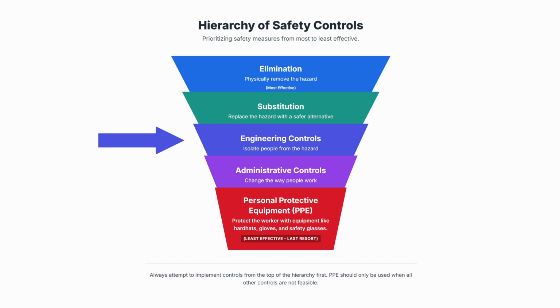Step 4. Develop mitigation strategies. There are several mitigation options that can be used to reduce occurrence and/or severity of a risk. Engineering controls, like physical safety barriers, emergency shutdown systems, or enhanced machine guarding, might be necessary. Administrative controls, such as updating procedures, training programs, and communication protocols may be appropriate.